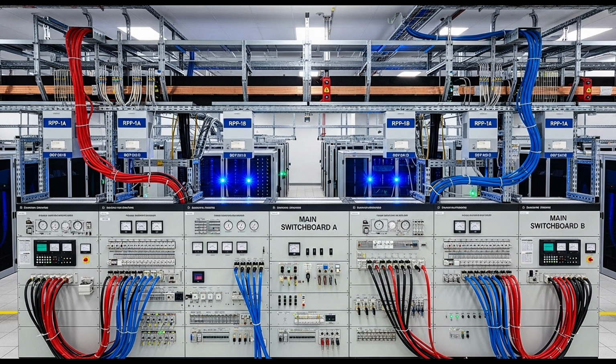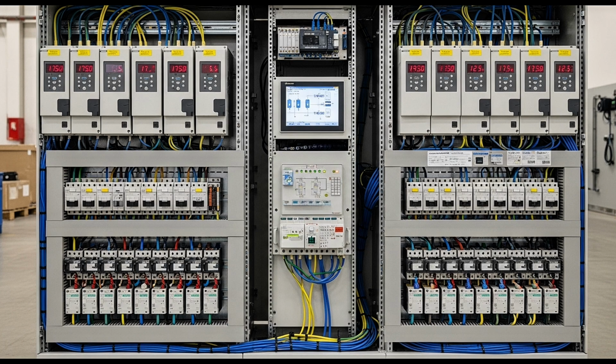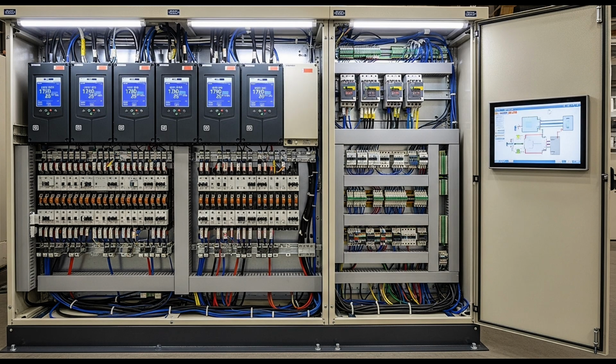Ground wires don't normally carry current. They're there purely for safety. Each outlet box, switch box, and appliance frame connects to the ground wire, which returns to the panel's ground bar. The ground bar connects to the neutral bar at one point, the main bonding jumper, and also to the building's